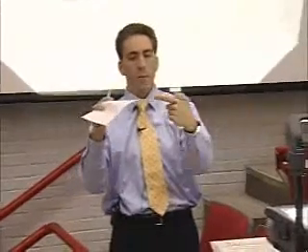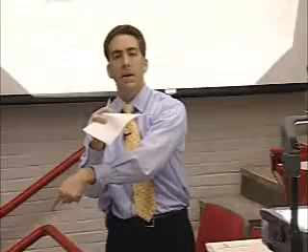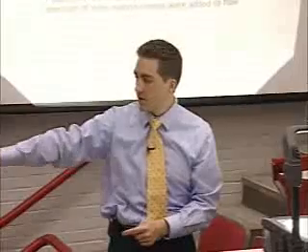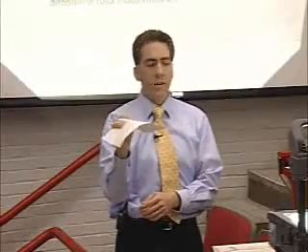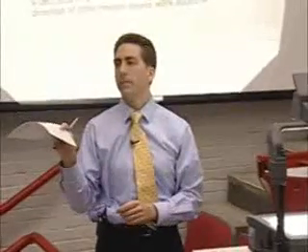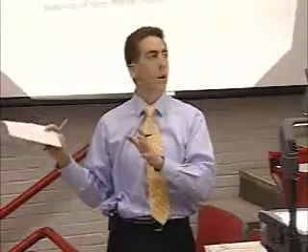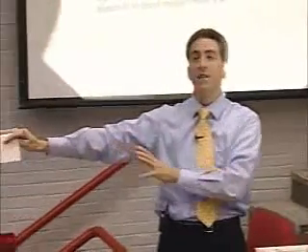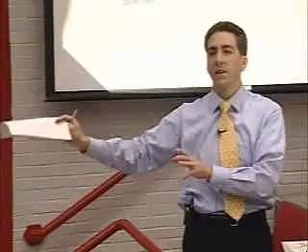I've got momentum coming in like this. I put the momentum down like that. I must get a force opposite to it. All right, so airfoils, and these are just spinning airfoils, change the direction of the flow, and that produces the forces. The only time that this does not hold is if you have stall and the flow separates from the blade. We're going to assume that this is a well-designed machine. You do get a lot of fancy kinds of stalls in these engines, but it's not the first thing you're going to try and solve. Right, so you're going to assume that the flow always leaves at the trailing edge angle.